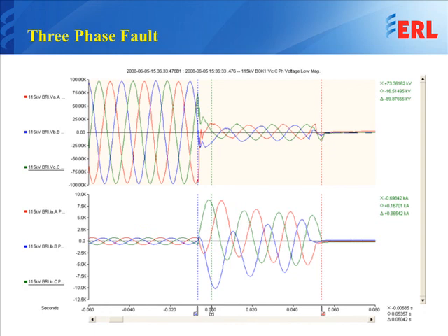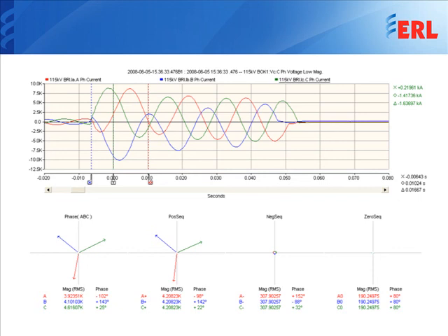Based on what we have just discussed, this is clearly a three-phase fault. As seen on the sequence circuit, we should only expect positive sequence components. In this case, we have about 4200 amps on positive sequence, about 300 for negative, and about 190 amps for zero sequence, which is probably inherent to the system.